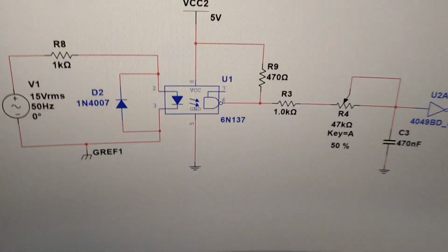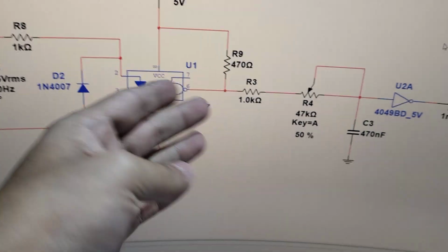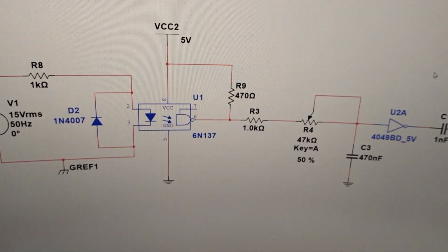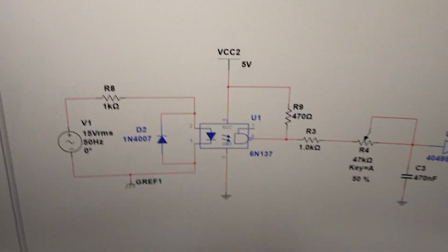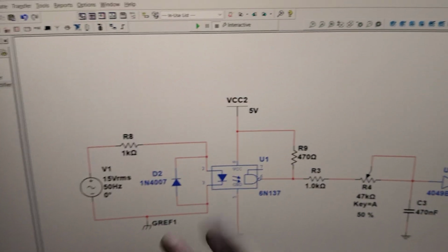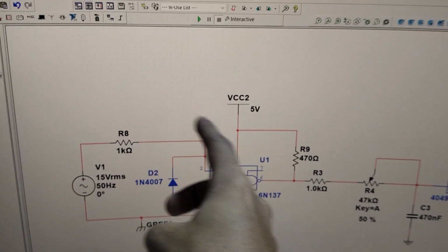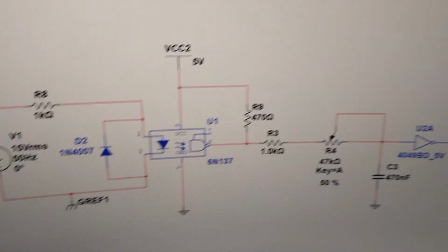So when this goes high basically in the positive half cycle, this is going to go low, because it's an AND gate here, you could see it, but generally it's a photo transistor. Either way, this output is inverted. And in the negative half cycle, it's a diode after all, but just for safety I put one in parallel. So in the negative half cycle, this diode is going to conduct, so nothing happens with the optocoupler as such. So we are only concerned with the positive half cycle.